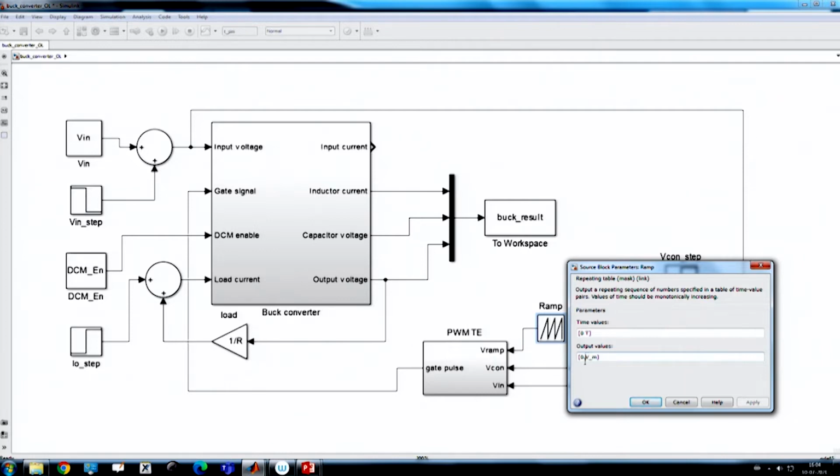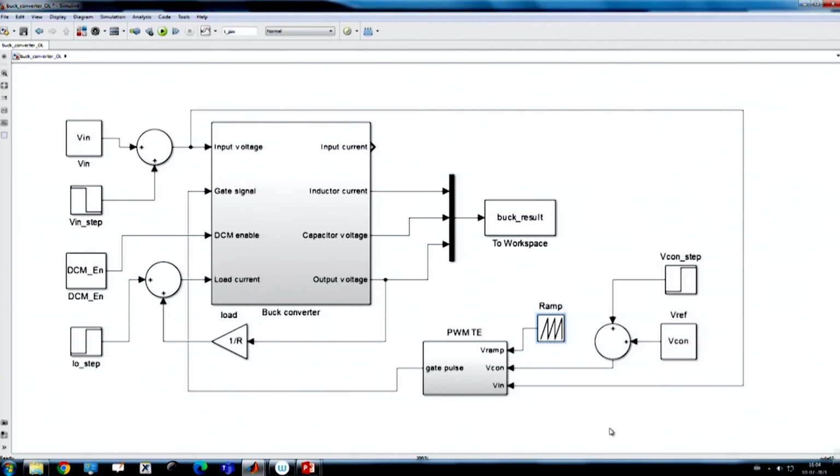Because we have discussed that if we want to run a DC-DC converter, we have to consider a sawtooth waveform, and if you want to generate an open loop duty ratio, then one way is to take a sawtooth waveform and compare it with a fixed voltage. If you compare, then it will generate the duty ratio, and we also need a latch circuit. Those things we have discussed.